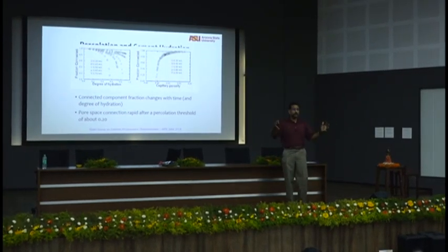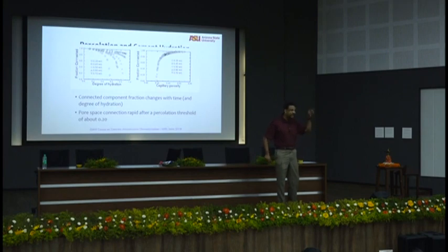Have any of you, you all do concrete mixture proportioning based on M.S. Shetty's book or some book? You do all the proportioning using the specific gravity of aggregates, all of that. Have you ever gotten in the first trial the right thing that you proportioned? No. Then what do you do? You adjust. Mistake. Any adjustment is a problem.